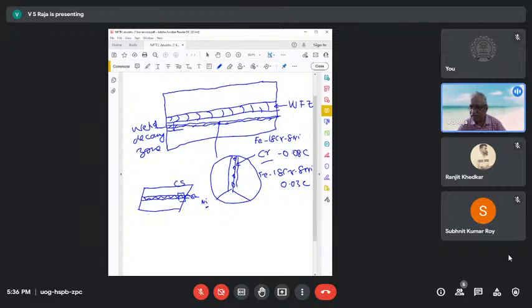Now, is it okay if we apply another paint coating over zinc to protect it from atmospheric oxygen at elevated temperatures? I found zinc-rich epoxy is applied as a primer on carbon steel surfaces operating at temperatures above 100 degrees Celsius, with another one or two coatings of non-zinc paint.